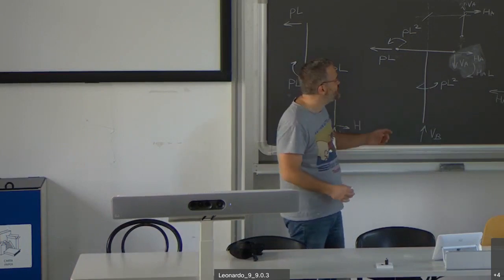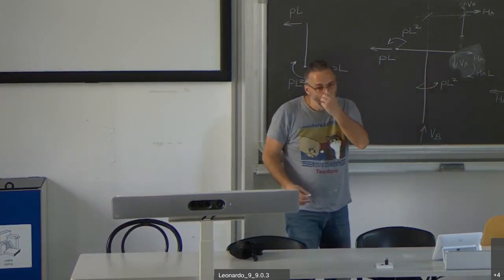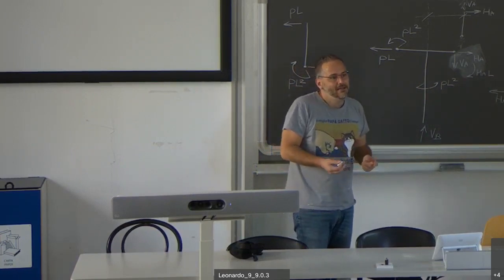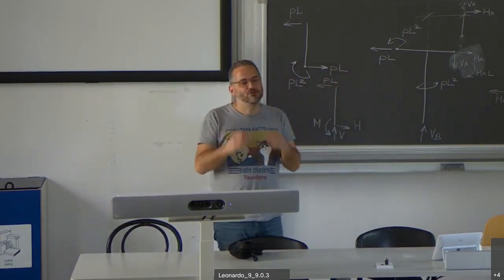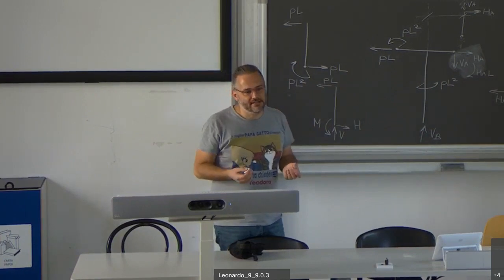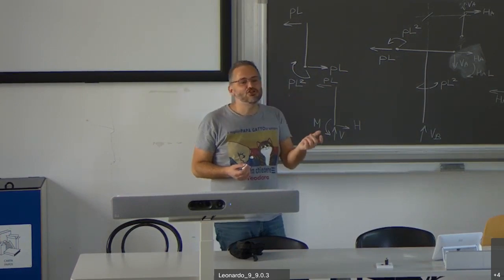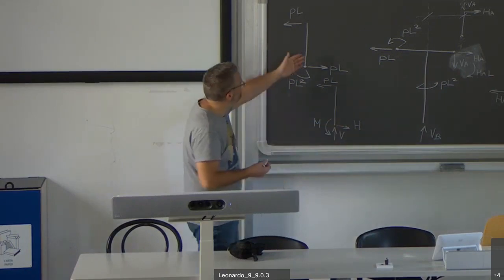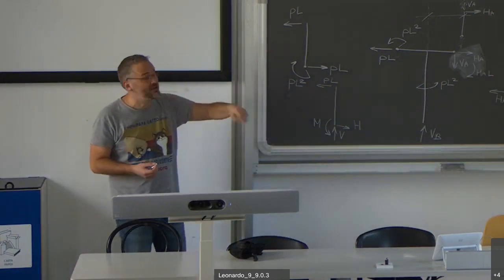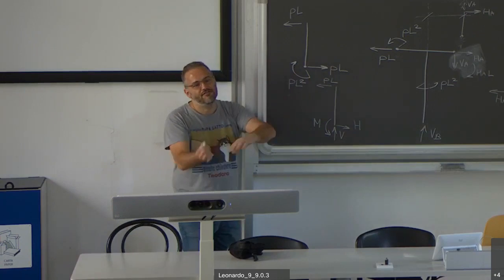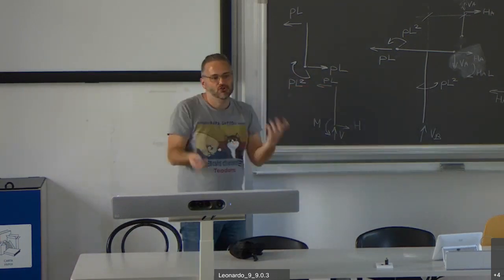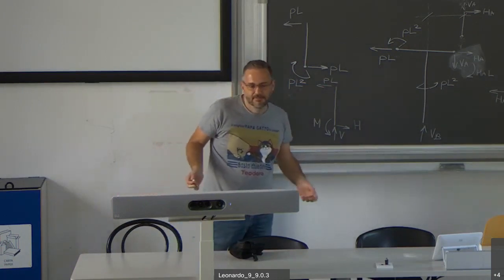I usually don't give concentrated bending moments as a standalone force because it's difficult to visualize them in reality. They are like a limit condition of something else, or, as I tried to explain by taking this portion away from the structure, they reflect the action of another part of the structure. So why not consider the whole structure? That's my point.